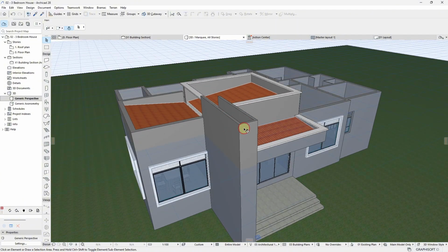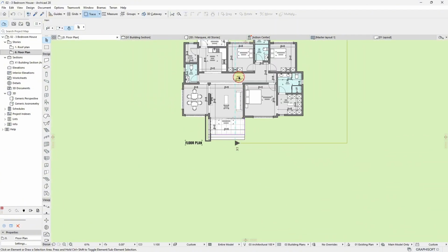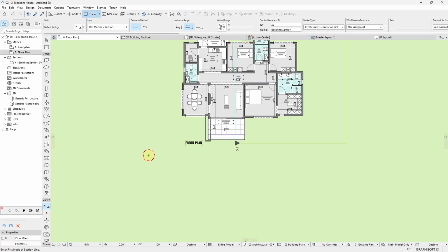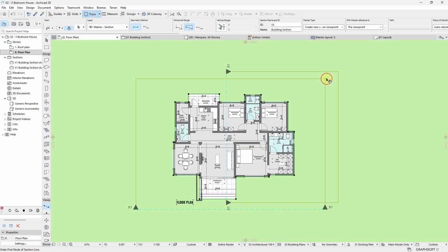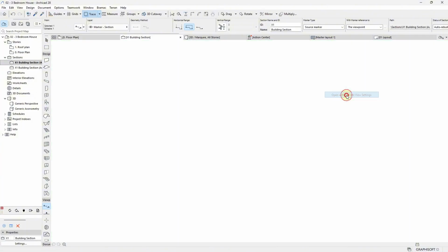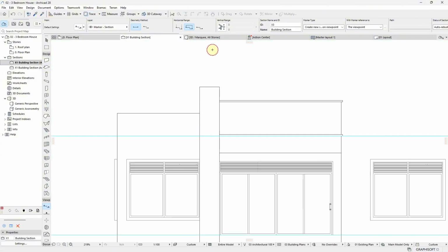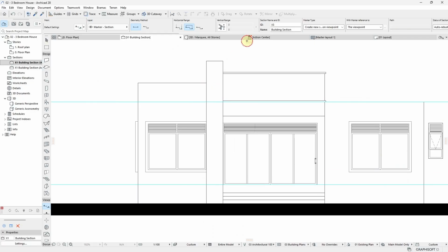And then for this design here, I'm going to come and make its height properly. So I'm going to have our front elevation here and select this, open this view. And then I'm going to get what you call a guideline from the floor level. I hover my cursor on the guideline, and then I just click on it. I move it up and I type in D. After putting in D, I want this to be as high as maybe 5.5 meters.